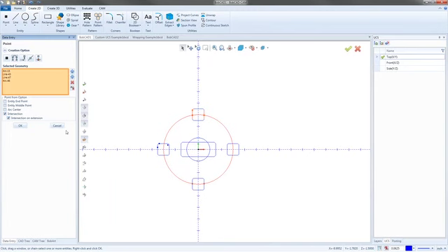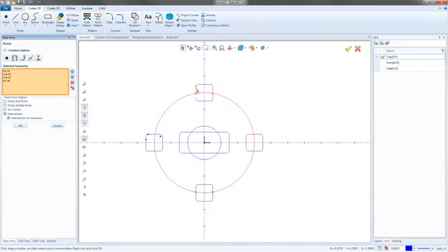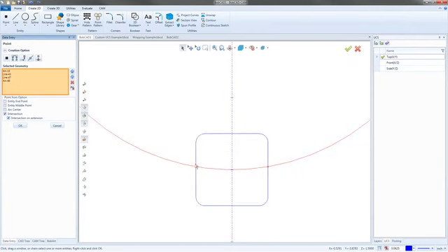The other option we have is called intersection on extension. So when you click this one, it's going to give you an intersection. If this line was extended any longer, it would give you the point for where it would connect on the other side. So in this case, because we're using an arc and we can hit it on both sides, it's intersecting on the top, and then on the extension, it's intersecting down here and here. So there's all the geometry for that.